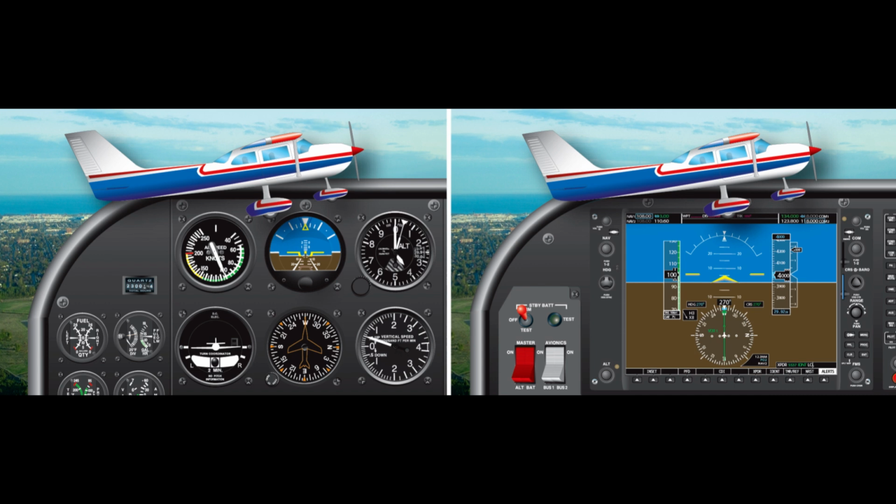The pilot should establish and maintain an appropriate constant bank during the turn. 3. The pilot should maintain a constant airspeed and constant rate of turn in both right and left turns. The coordination of all flight controls is a primary factor. All the factors that affect the airplane during level constant altitude turns affect the airplane during climbing turns.